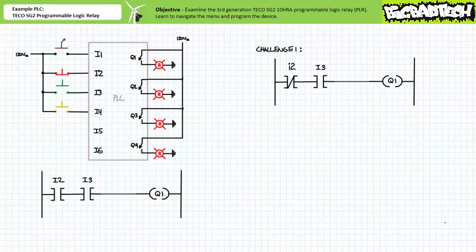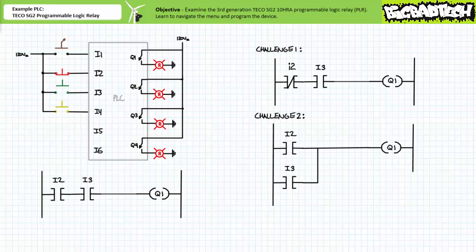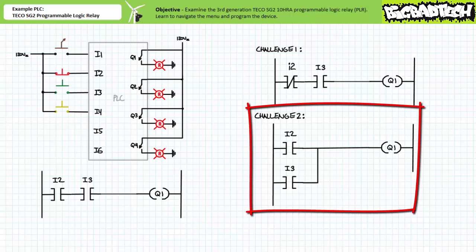Put your thinking cap on and figure out how the make and break functions respectively respond to the deactivated and activated state of the associated input devices. Think beyond colors. Red doesn't necessarily mean stop anymore. If you've got a PLC available, program it and see if your expectations match reality. Here's a quick hint. To change the logical operation of a contact from make to break in a program, press Select.